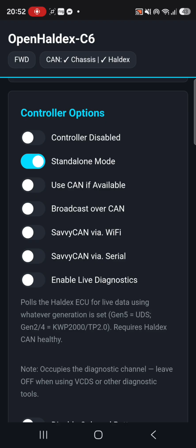So that's why I've added that feature in. However, this occupies an extra CAN address. So you might find that if you get a sporadic warning light, it's probably because this setting is enabled. It doesn't always need to be enabled. It should only be enabled if you actually do know what you're doing.